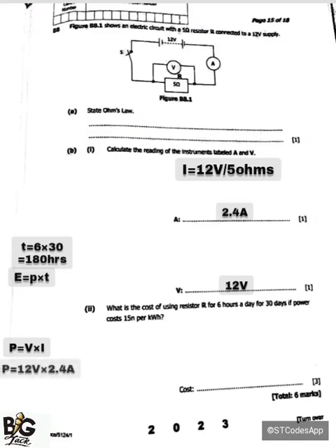So in this question, we have power is equal to, what is our voltage here? In this diagram, we have 12 volts. Then the current, I'm going to use the current that I've already found in question B, Roman numeral number 1. The current here we have 2.4 amps. So power is equal to 12 volts multiplied by 2.4 amps. Then the answer is going to be 28.80 watts.